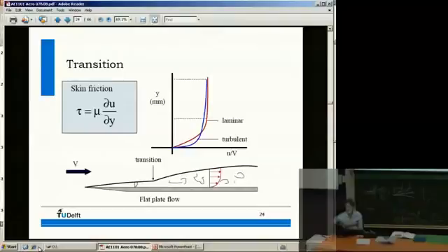Now let's look again at our boundary layer. A laminar boundary layer, that's the red one, looks like this. It's not so thick. Up here you have the free stream velocity, but it's not very full here. While the turbulent boundary layer is thicker, so it takes longer before you have the free stream velocity. But due to all these eddies close to the object, it is much fuller. So here you can already see that indeed skin friction is higher for turbulent flow, right? Because this one is less steep.